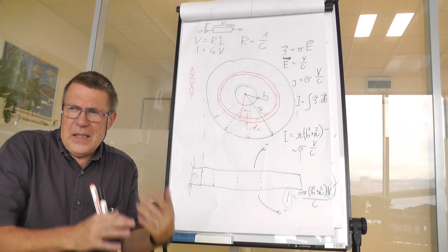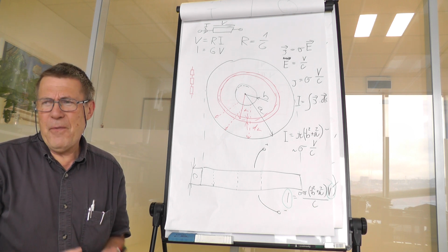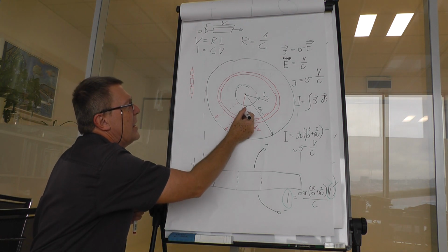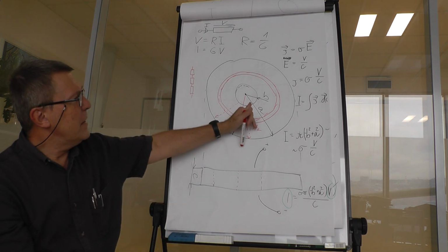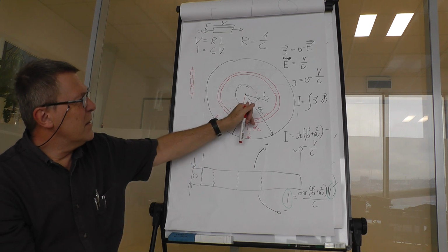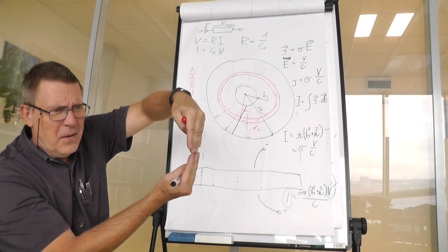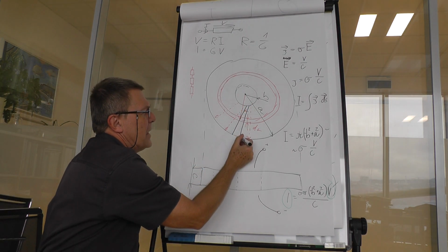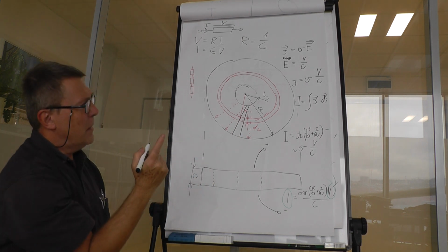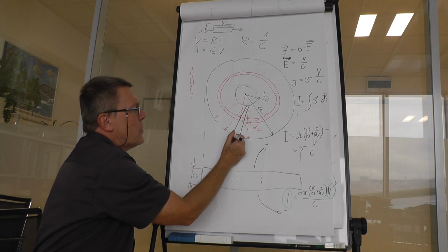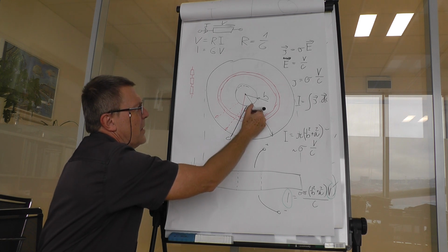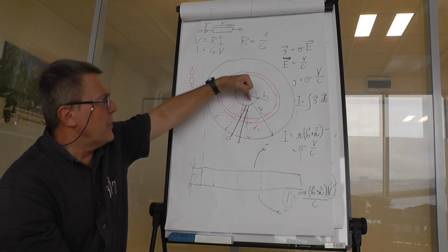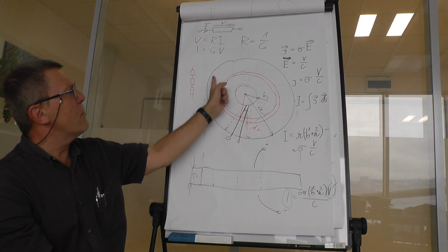Well, in order to have another way of exploitation, we would need a very thin saw, and we would now cut the disk with a very thin cut, so that now we have interrupted the disk. We have a kind of C, but with a very thin dividing layer here. And I will magnify it a little bit, so we have a very thin but non-conductive cut here, with one metallic layer here and the other metallic layer contact here. So now we will have again a resistor, but instead of having the current flowing from inside to outside, the current would run around the disk.